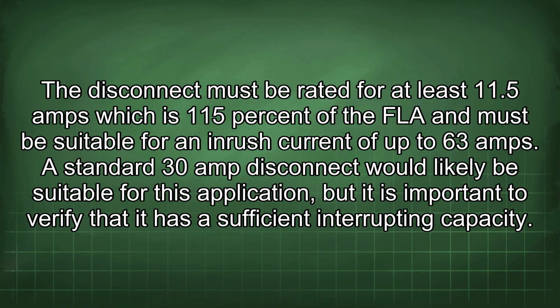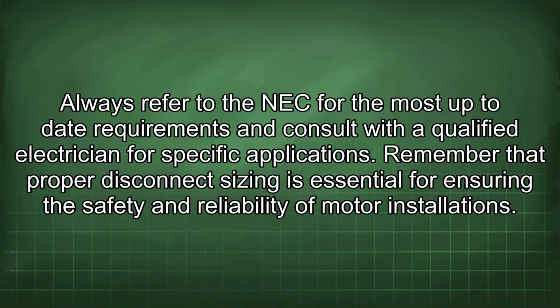A standard 30 amp disconnect would likely be suitable for this application, but it is important to verify that it has a sufficient interrupting capacity. Always refer to the NEC for the most up-to-date requirements and consult with a qualified electrician for specific applications. Remember that proper disconnect sizing is essential for ensuring the safety and reliability of motor installations.